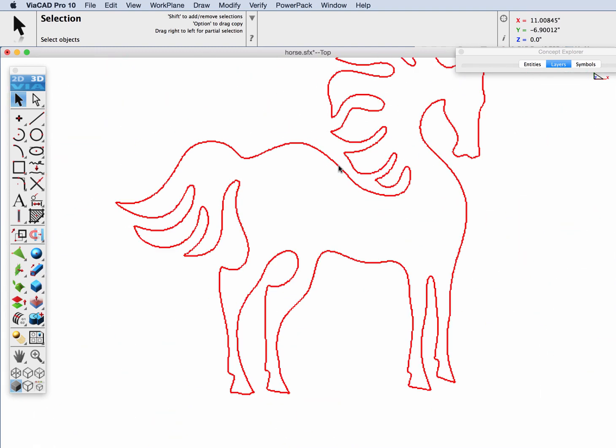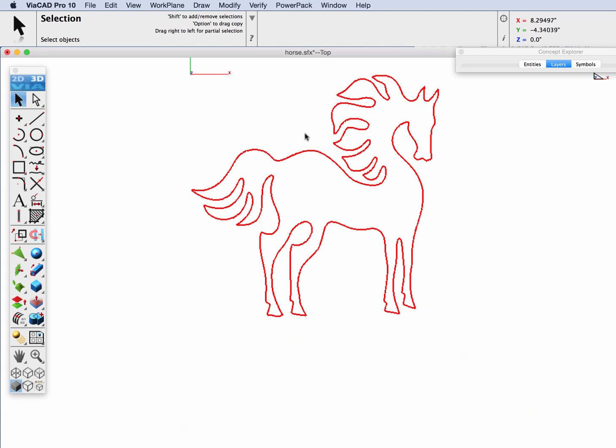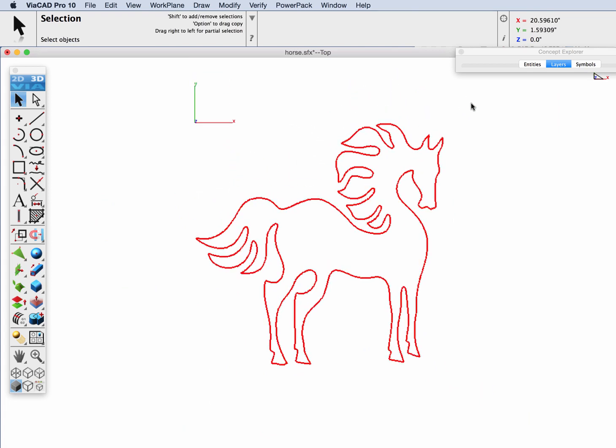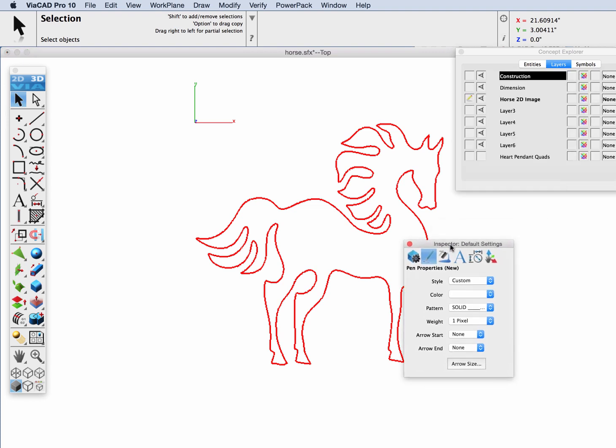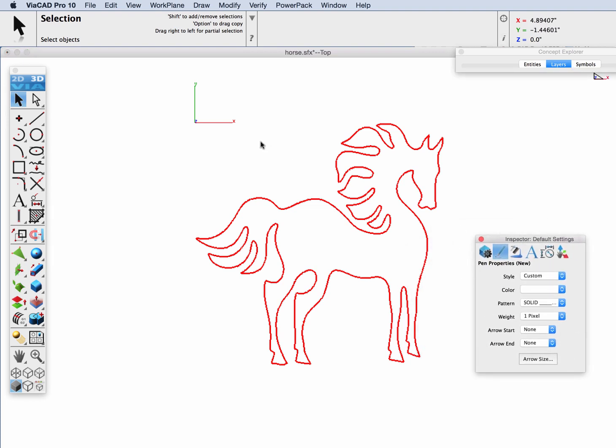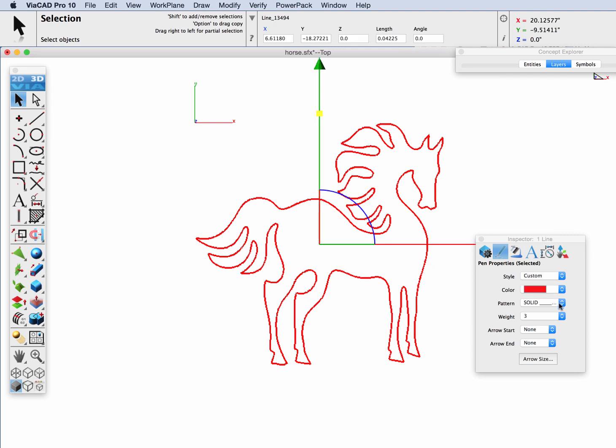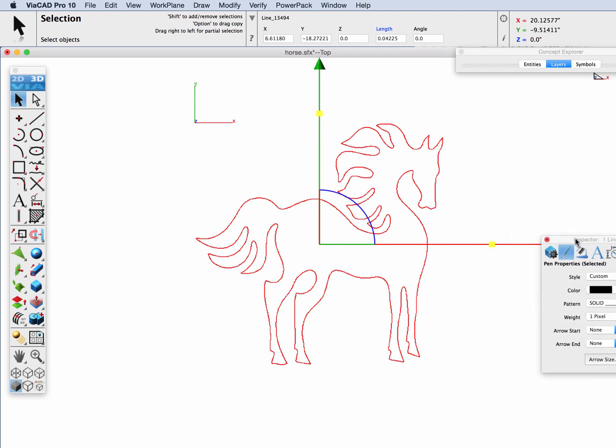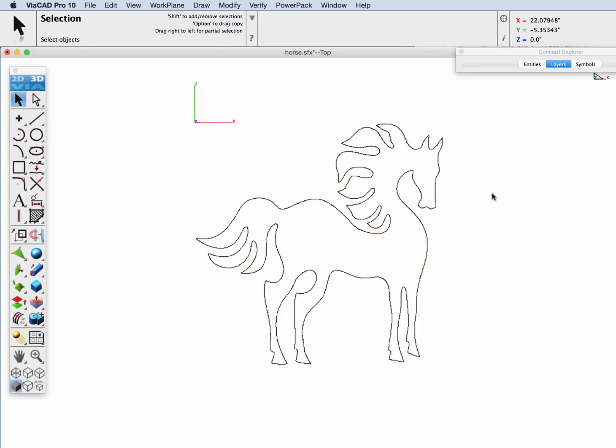And what we would like to do is smooth this. So let me show you what I would do to smooth this. First, let's go to the pen color attributes, and let's change the pen color attributes for this to black and a pixel width of 1. The show free edges always does the thick red lines.